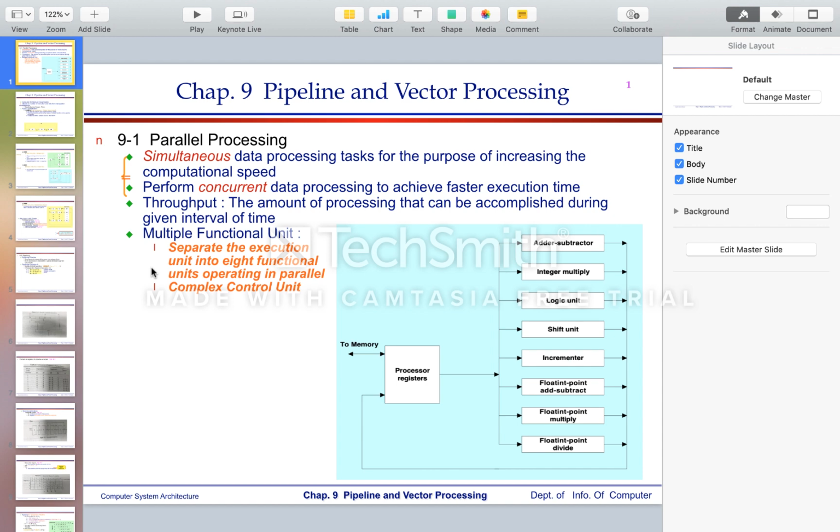So on the basic level, if we consider registers which are used for storing data, either we can have shift registers which store our data in serial fashion, one bit at a time, or we may also have registers with parallel load capabilities which store all the bits in a word in parallel fashion.